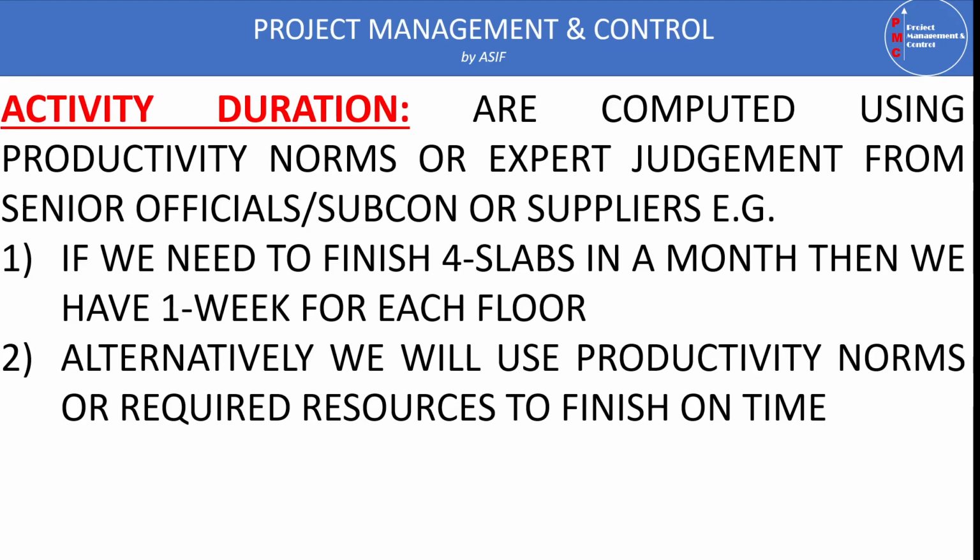Similarly, if you go for block work, before block work we have a layout and engineer inspection. This layout and engineer inspection will not take too much work, so we can include all of this in one activity like block work. But concreting work can be defined into three or four activities, as I said a little before, like for example fixing of formwork, laying of steel reinforcement, and then pouring.